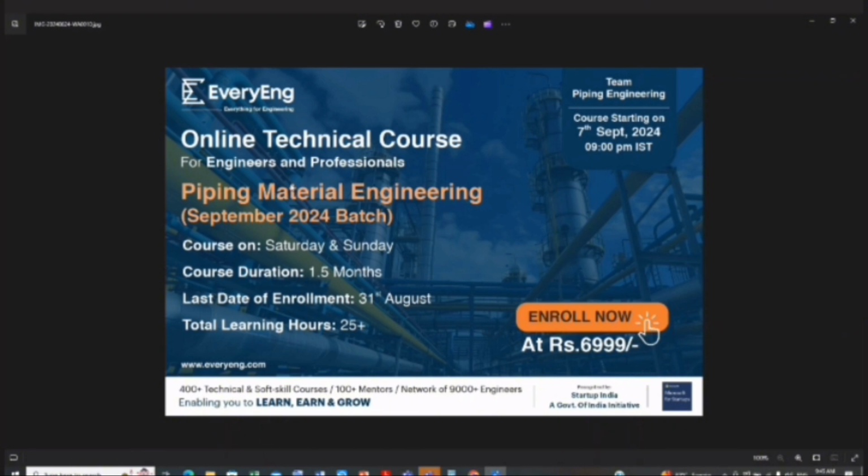Any other questions? Sometimes it is 1.5 mm, sometimes it is 1.6 mm. So it depends on the licensor actually. The corrosion allowance value comes from the licensor.